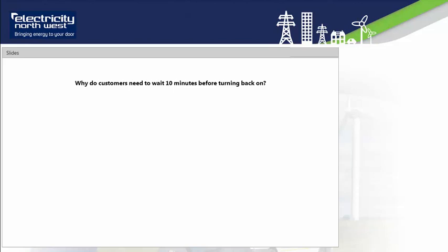You mentioned data quality issues in the fault level assessment tool. Can you give me more detail on what these issues were? Yes, so the issues in terms of the tool were that to carry out the fault level assessment, we're using fields of data that haven't really been used before. There's a large amount of data cleansing required. So that data has been cleansed, and the fault assessment tool does work, but it's an ongoing thing really to keep the data up to date so it functions correctly. That's why we're looking at the viability of using the assessment tool post trial.